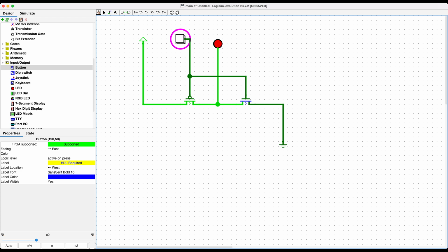This is what's called a CMOS process, for complementary metal oxide semiconductors. The NMOS and the PMOS play a complementary role in terms of the electrical properties, and so the design rule will be you put them in pairs. Every time you have an NMOS, you have a complementary PMOS and vice versa.